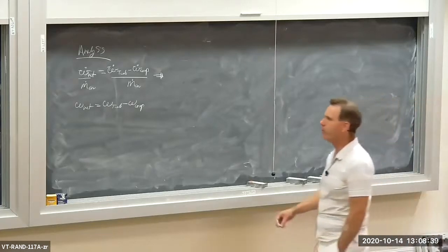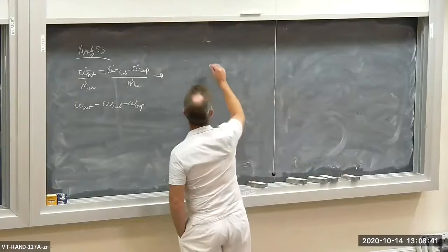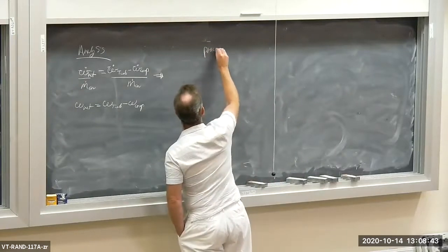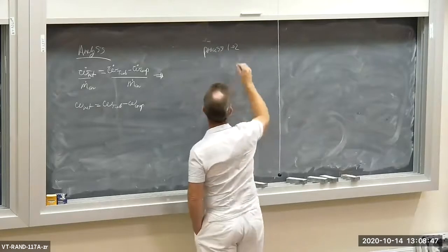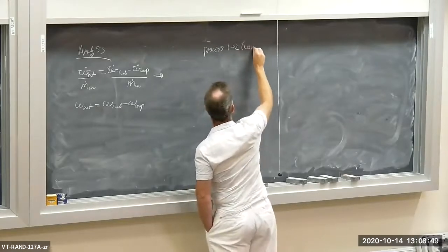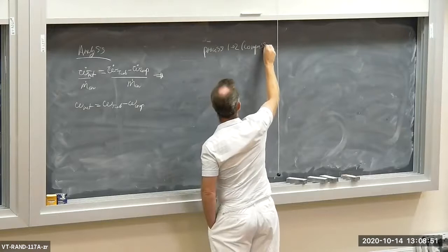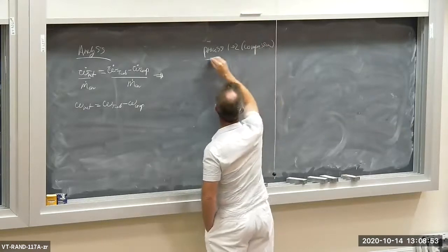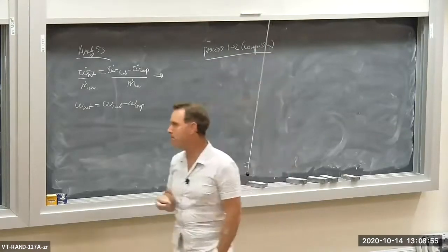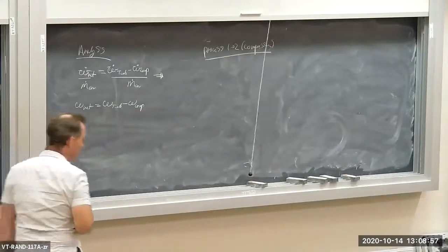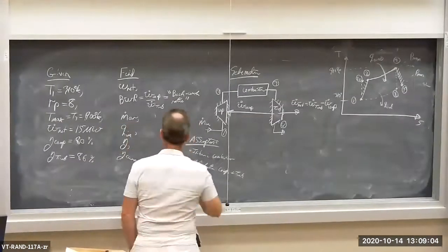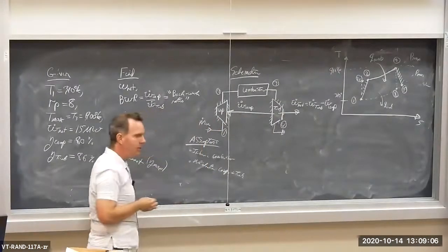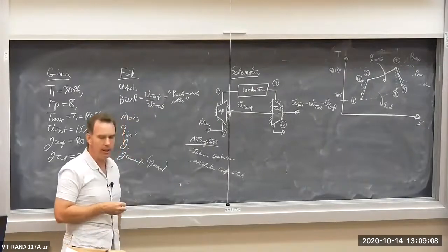Okay, well, let's find the compressor specific work first. So let's look at process 1 to 2. That's the compression process in the compressor. So if I apply the energy balance to my open flow compressor, it's adiabatic.